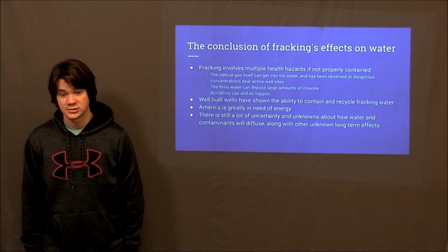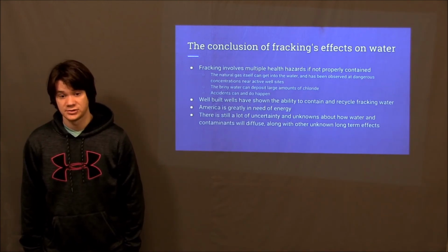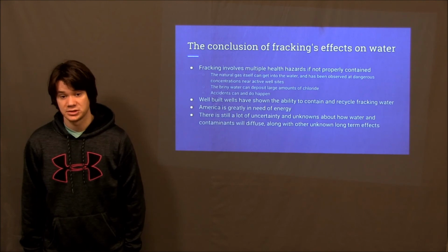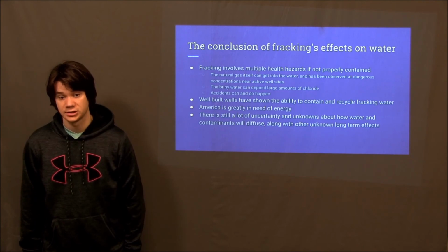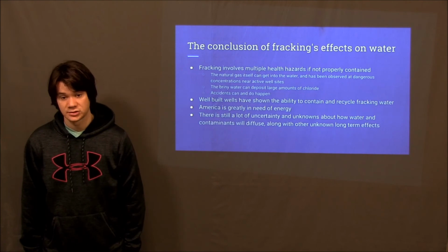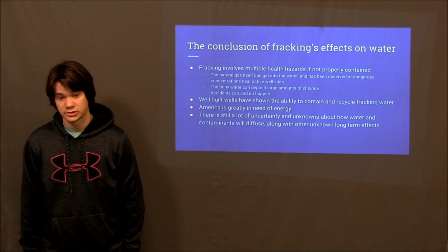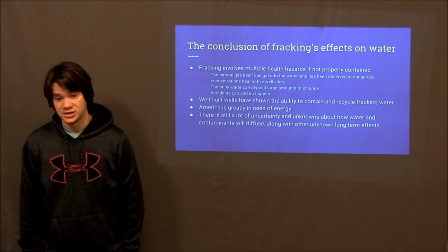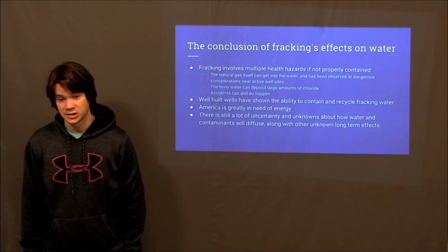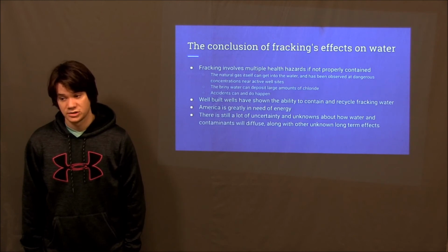Natural gas is extremely advantageous for America to use as an energy supply because it can be toggled on and off quickly through natural gas turbines. Many power plants, such as coal and nuclear, are baseload power plants and will put out a large constant amount of power. They are inadequate at switching their production to meet rapid fluctuations in demand. Because of this, natural gas burnt in small turbines is incredibly effective because it can be controlled how much is being dispatched.